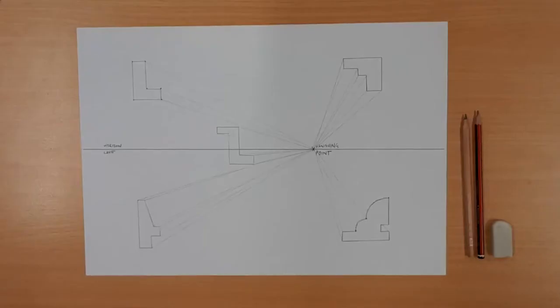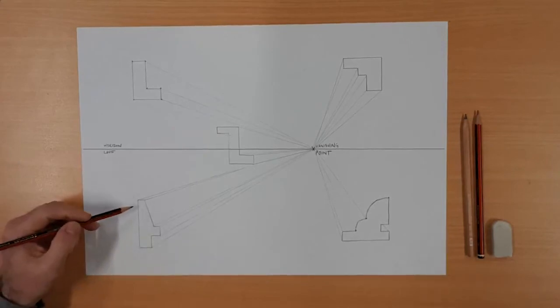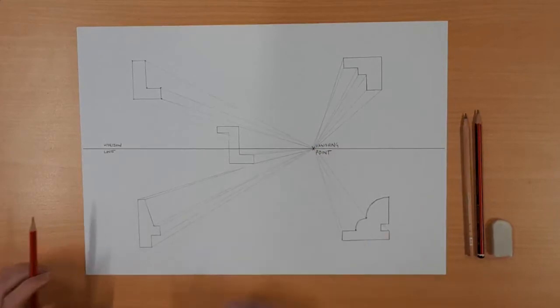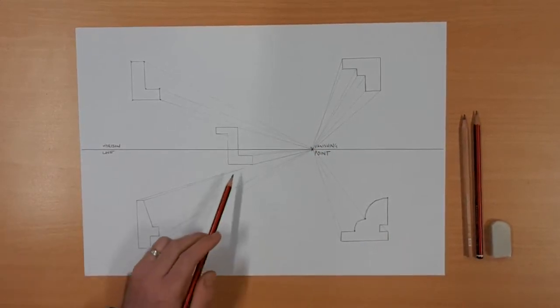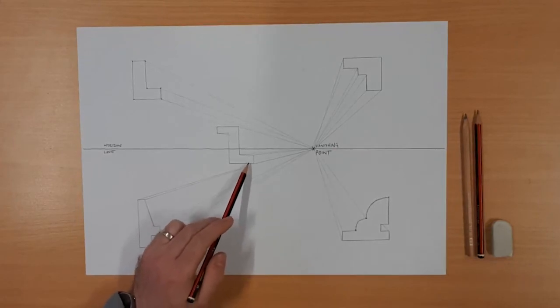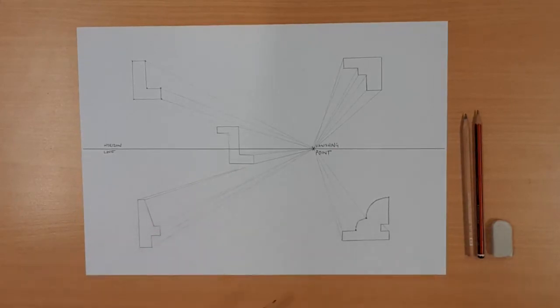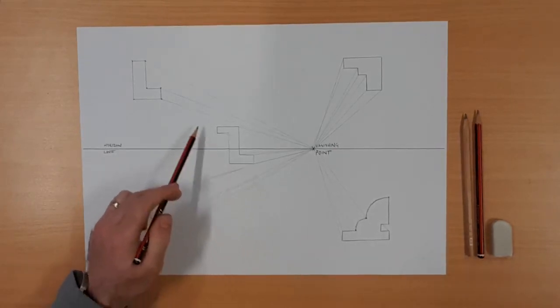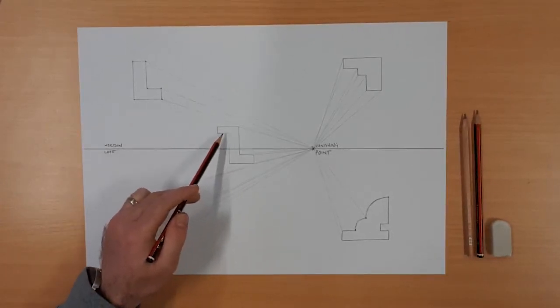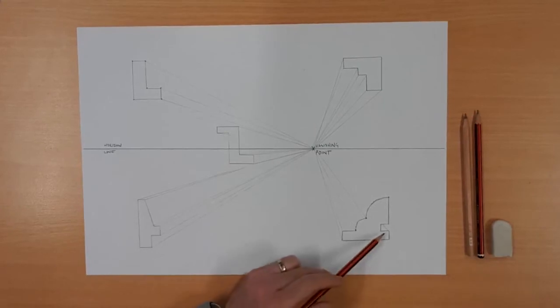And we're back, we've completed that. So we've now depicted the depth, so that depth always recedes back to the vanishing point. I just want to reiterate that there's no point continuing these lines any further and having it clash with that, because it's just going to cause confusion. So you can see I haven't completed the line fully there, even within this block here, because we're saying this is a solid front block located over here, and I've just left this last line.